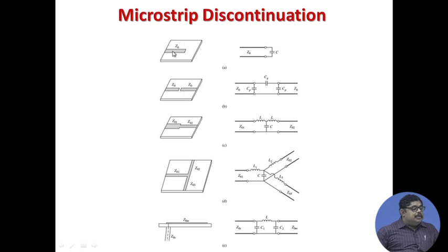In a normal microstrip line the whole thing should be continuous, but here we are keeping a gap, that is giving rise to a C. Now, with two things in between a gap, that gives rise to a pi capacitive network.